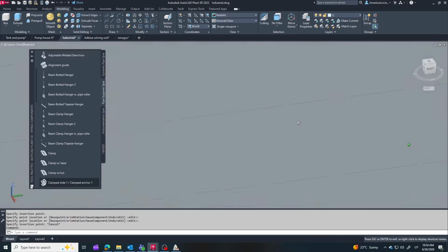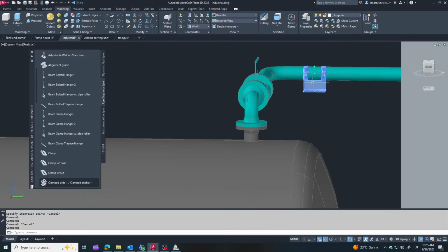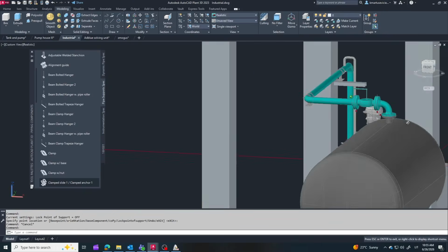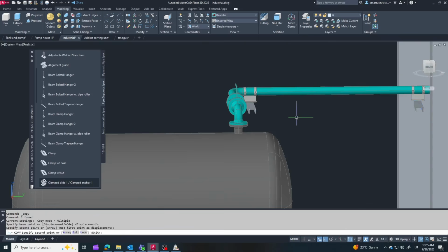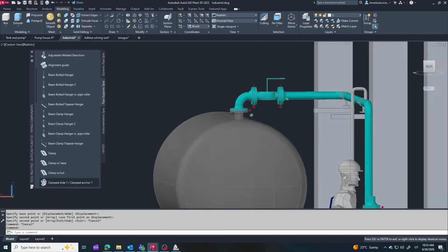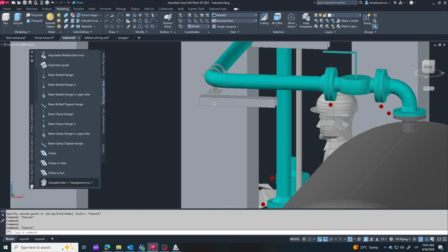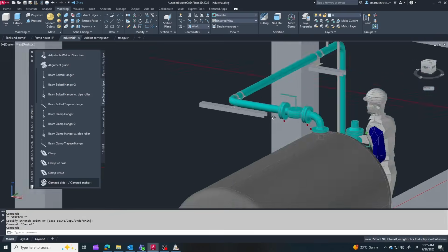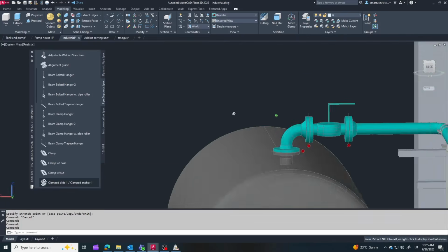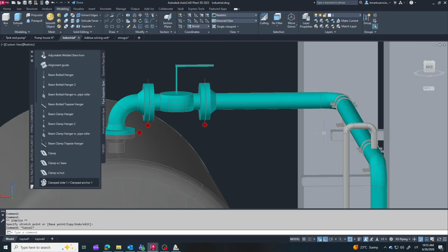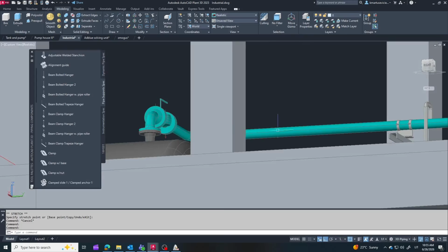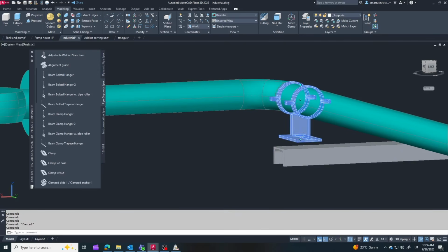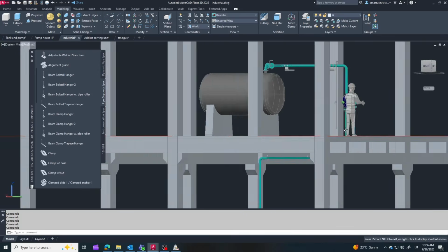One important rule: never treat an equipment nozzle as a pipe support. Equipment nozzles are designed to connect the piping to the equipment, not to carry the weight of long pipe runs. If the piping isn't properly supported, its weight, together with the fluid, valves, insulation, and thermal loads, is transferred directly into the nozzle. That can lead to excessive stresses, leakage, damaged flanges, or even damage to the equipment itself. Always transfer the pipe loads into the building structure, not into the equipment.